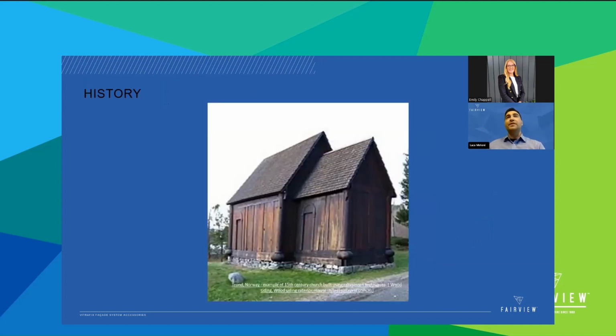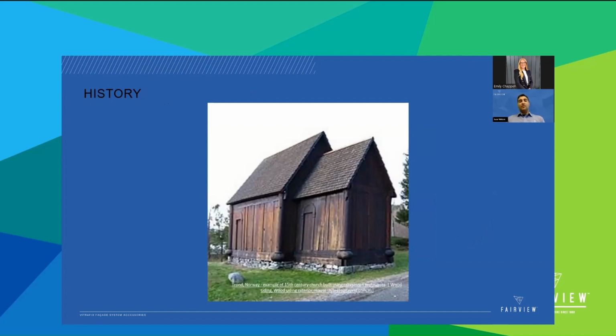A bit of history about rainscreen systems: protecting the walls by means of a screen as a principle is definitely not a recent idea. The concept of a rainscreen system goes back centuries, originating in Norway. These earliest rainscreen systems were initially a mere intuition, created through experimentation rather than through scientific research or knowledge, using wood cladding with tight seams between boards, leaving an air cavity behind, with ventilation at the top and bottom of the facade to enable rainfall to flow away and moisture to evaporate into the eaves and above, to protect stone walls in modest buildings first.